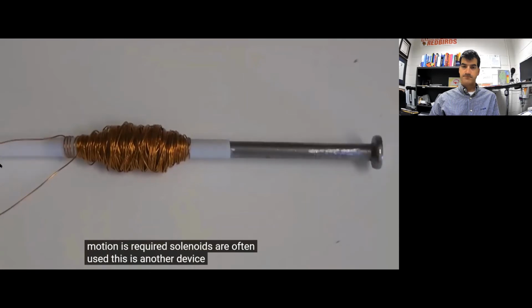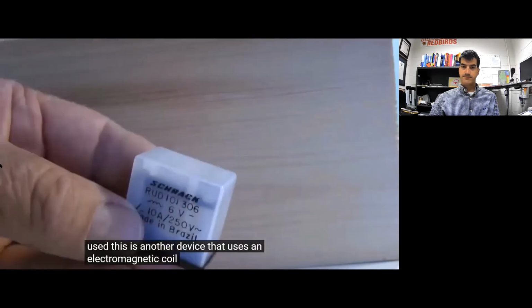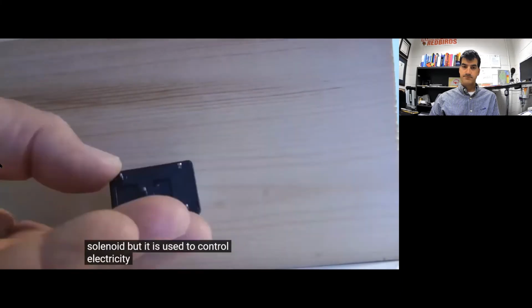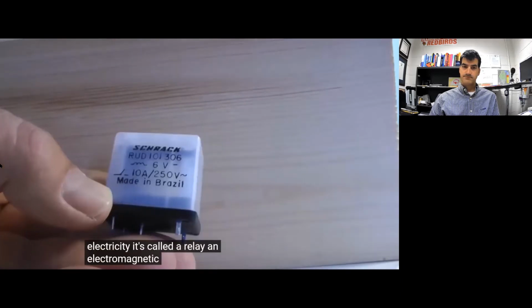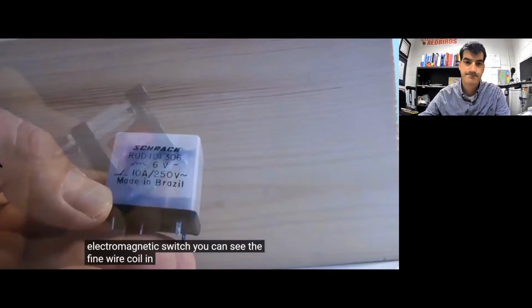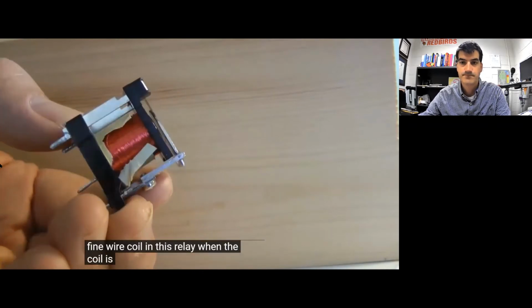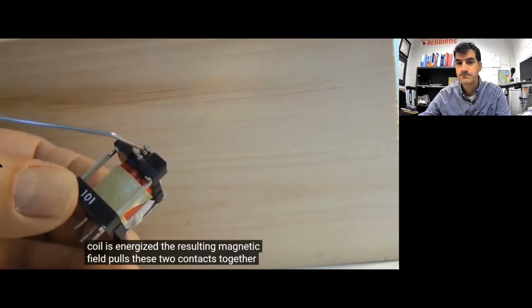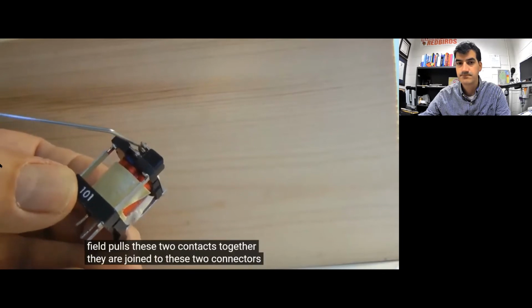This is another device that uses an electromagnetic coil. It is similar to a solenoid, but it is used to control electricity. It's called a relay, an electromagnetic switch. You can see the fine wire coil in this relay. When the coil is energized, the resulting magnetic field pulls these two contacts together. They are joined to these two connectors.